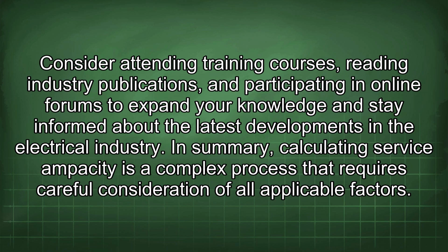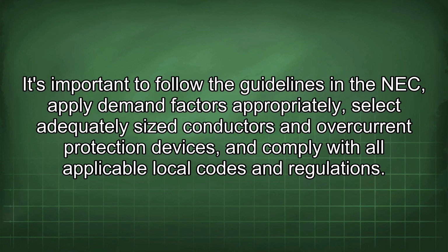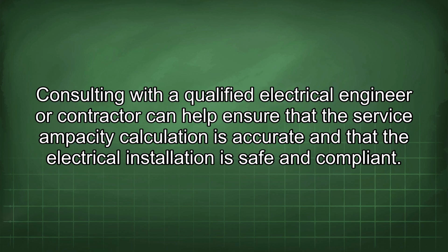In summary, calculating service ampacity is a complex process that requires careful consideration of all applicable factors. It's important to follow the guidelines in the NEC, apply demand factors appropriately, select adequately sized conductors and overcurrent protection devices, and comply with all applicable local codes and regulations. Consulting with a qualified electrical engineer or contractor can help ensure that the service ampacity calculation is accurate and that the electrical installation is safe and compliant.